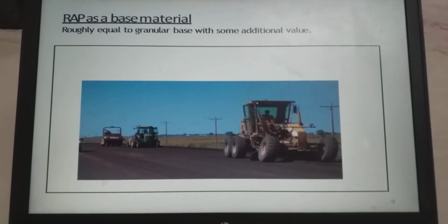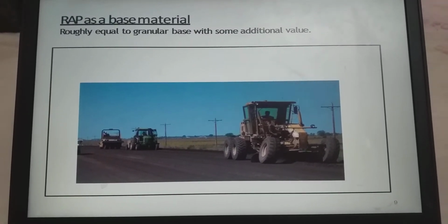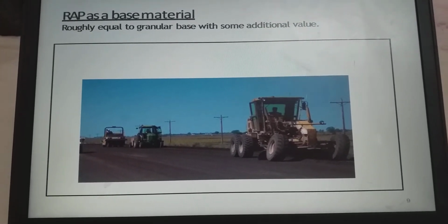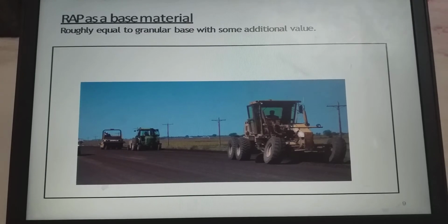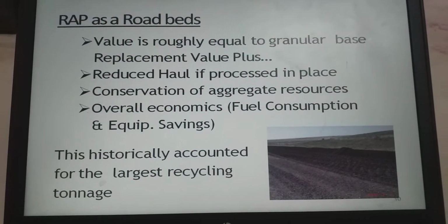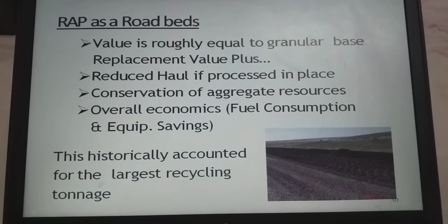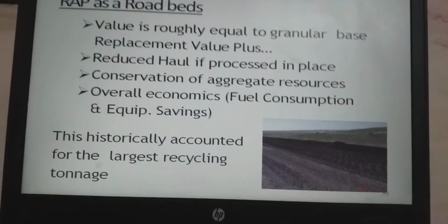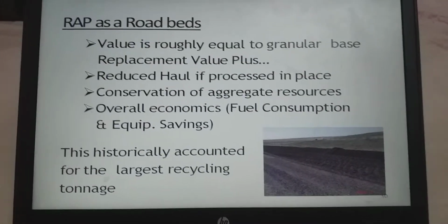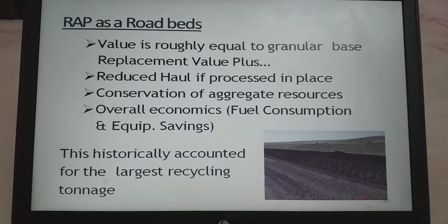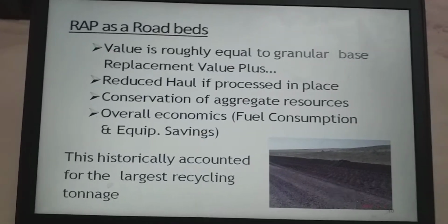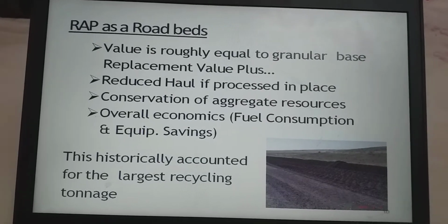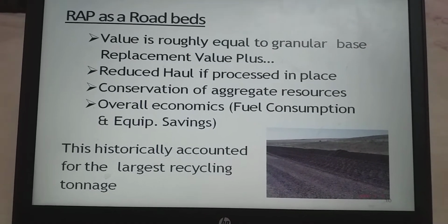Now see if we use the reclaimed asphalt pavement as a base material, see the picture where they are using the asphalt pavement. Then if we use the reclaimed asphalt pavement as a road bed, what benefits will we get? The value is roughly equal to the granular base. Means if we recycle the earlier pavement, then the value of new and old is roughly equal.